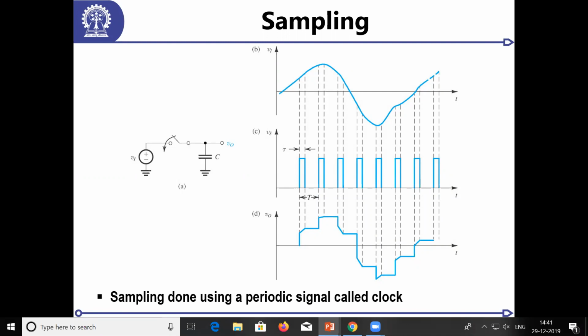Now this R, I can manipulate the resistance of a transistor using what technique? If I want to reduce the resistance, I will increase the width of the transistor, and keep the channel length at minimum. So if I am going to a higher and higher sample rate, and I keep this capacitor fixed at a particular value, then as a designer I have only the width of the transistor to manipulate to get to the required sampling accuracy.